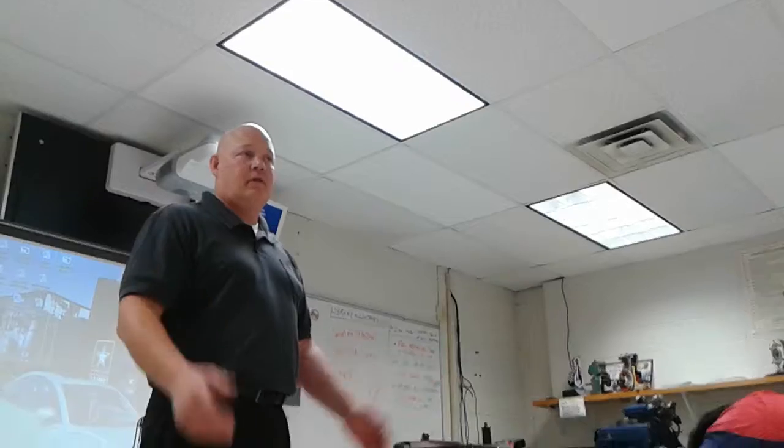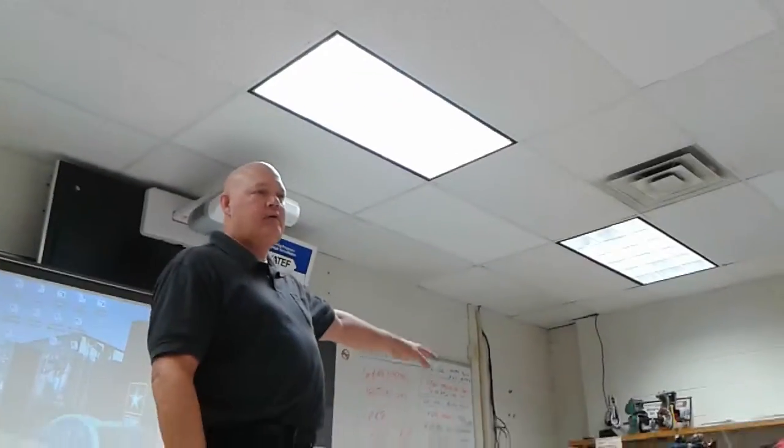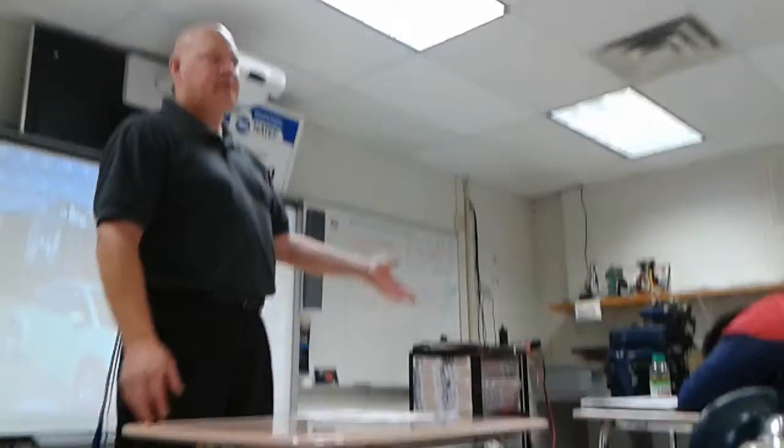If you can work on stuff, you can have yourself a pretty good running lawnmower. Same thing with the carburetor in lawnmowers. As I was telling you guys last unit, the carburetor is like 90% of the problem. Today's magnetos and electrical systems on the lawnmowers, 99.9% of the time, they never fail. On older things that used to have coils like this and older point systems, they used to have problems. They used to do a lot of maintenance.